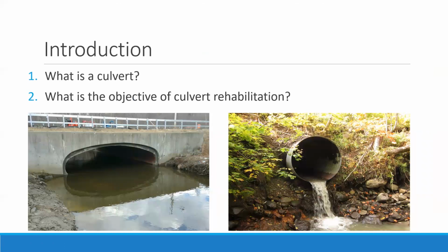So what is a culvert? Well, when we hear the word infrastructure, most people think of roads and bridges. However, supporting those roads and bridges are countless drainage structures, most of which can be classified as culverts. A culvert is a buried pipe, box, or arch structure that is open at both ends to convey water on a roadway or a railway. Culverts can be structurally similar to bridges, but are defined as having unsupported spans of less than 20 feet.